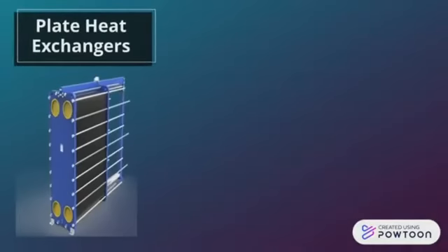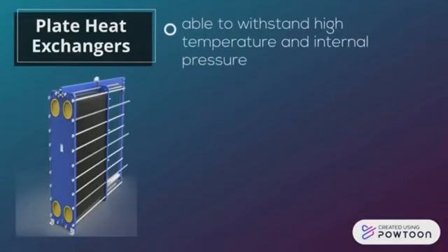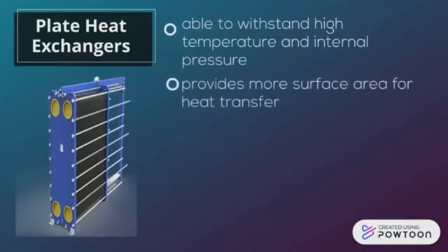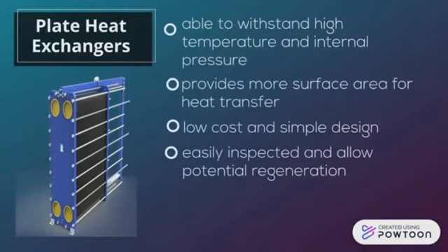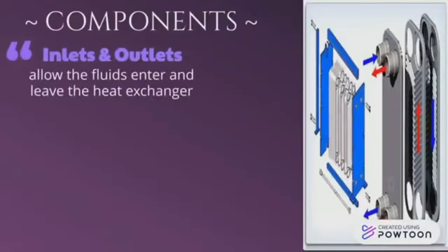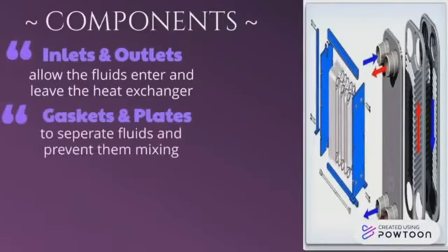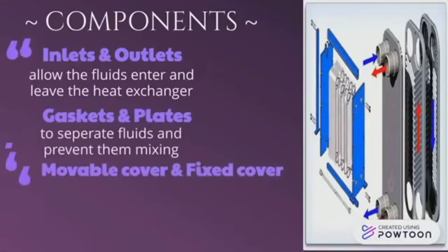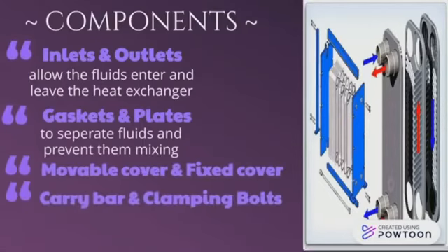Plate heat exchangers are able to withstand high temperature and internal pressure, provide more surface area for heat transfer, have low cost and simple design, are easily inspected and allow potential regeneration. Inlets and outlets allow the fluids to enter and leave the heat exchanger, gasket plates separate fluids and prevent them mixing, movable cover, fixed cover, carry bar, clamping bolts, and guide bar.